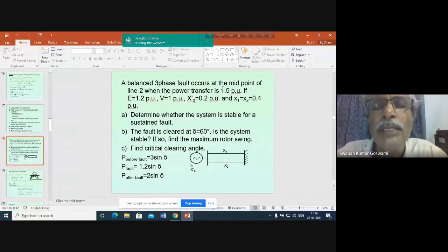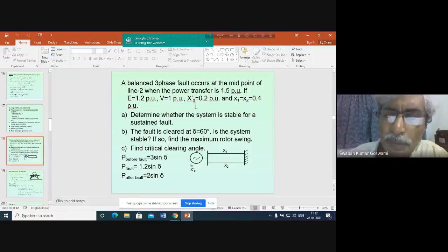What happens if the disturbance takes place? Suddenly there will be an increase in the armature current. So let me discuss this transient reactance and subtransient reactance in brief, so that it will be better for me to explain things. When suddenly there is an increase in the output current of the generator, armature current increases, which means armature flux also will increase. But obviously in a magnetic circuit, flux cannot increase instantaneously. It is opposed by the system.